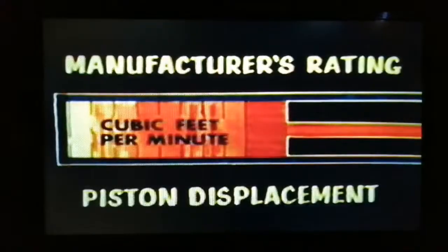Before we continue, let's discuss briefly how manufacturers rate reciprocating compressors. Ratings are in terms of piston displacement. This is the amount of air which would be delivered by the first stage piston if it were 100% efficient. The quantity of air is expressed in cubic feet per minute.